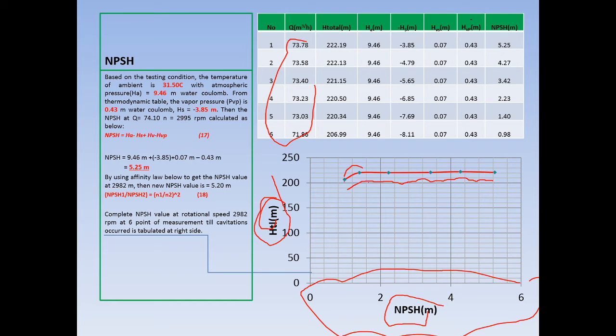It's easy to understand that this is when cavitation happens. The discharge head should be reduced by 3%, as I explained to you. And in this area it's quite an interesting graph. For one point of flow capacity, you make an NPSH. It's not NPSH required yet. It's NPSH in relation to head total.